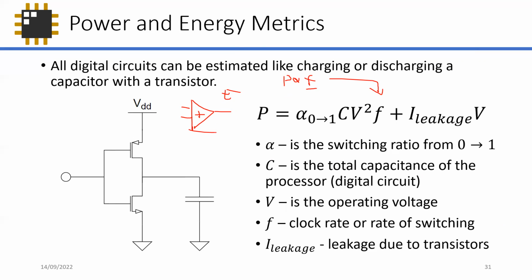For now, one of the key things that you have to understand is that most digital circuits, like this simple logic inverter over here, we estimate the power depending on how much you charge the capacitor. So you actually charge it by some fraction or ratio. If you have an inverter that's processing in some big processor, how much percentage of that inverter is actually toggling?